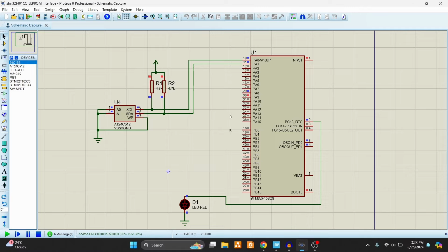We have not connected any oscilloscope to monitor the I2C sequence, that is start, stop condition, how data is written, but I'll make sure that I explain it thoroughly. Once we can see a few transactions on the clock and data pins of the I2C of the EEPROM device, then we will check what contents are written.